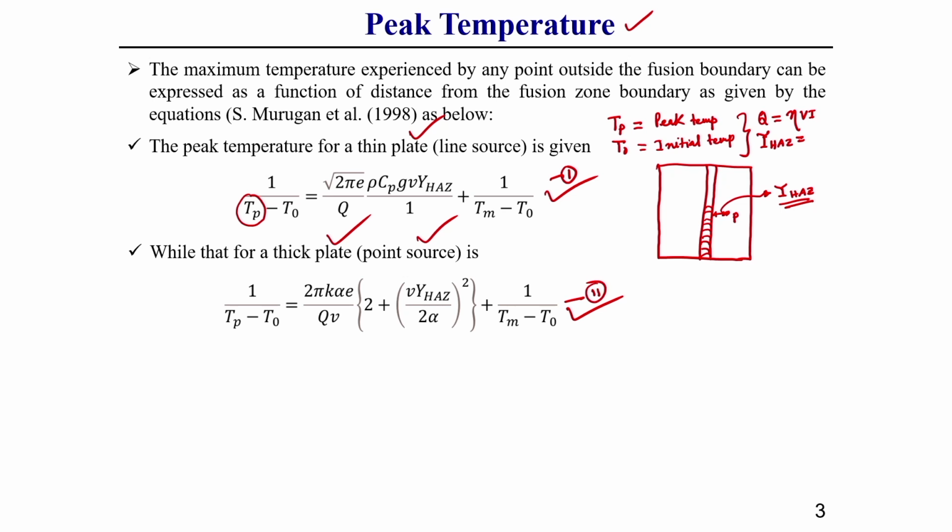This equation has very wide application. What can we estimate by this equation? First, a very important thing, the size of the heat affected zone, HAZ. It also gives an idea of the effect of preheat temperature, or T 0, the initial temperature.